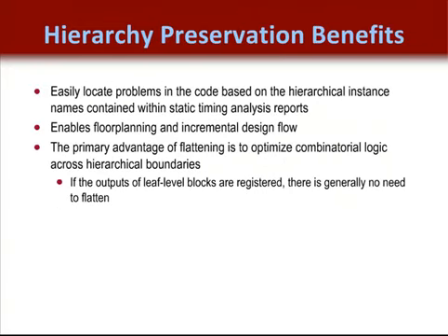Maintaining your design's hierarchical boundaries yields numerous benefits, as I mentioned a moment ago. It makes it easier to locate nodes when you are simulating probing with ChipScope, for example, or simply reading a synthesis or timing report. However, what many customers don't realize is that it also enables floor planning and the use of incremental design flow. Incremental design allows users to maintain the place and route solution found for part of the design and only repeat place and route on components that fail to meet timing or have changed logically.